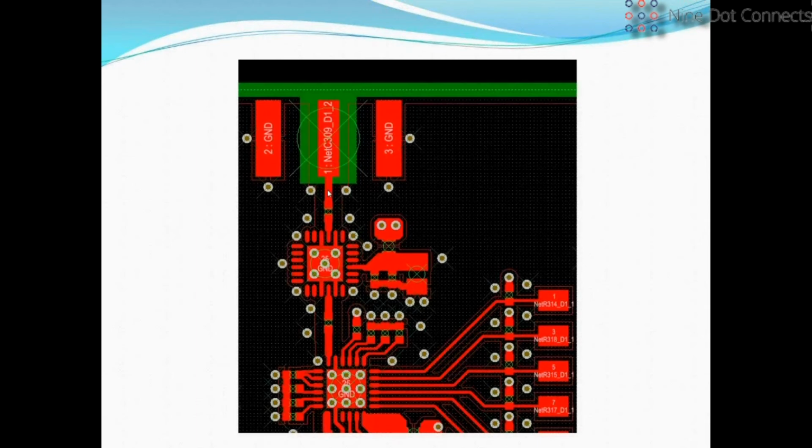Obviously, this trace right here is 50 ohms. You've already done your calculations. You understand that ground is X amount of mils or millimeters away. But as you transition to the larger feature on your board, you should adjust the ground such that it is accommodating the 50 ohms that's desired. By not including this in your designs, you will increase the capacitance, affecting the overall circuit, and not getting the 50 ohms that you had planned on. So that's the purpose of this slide.